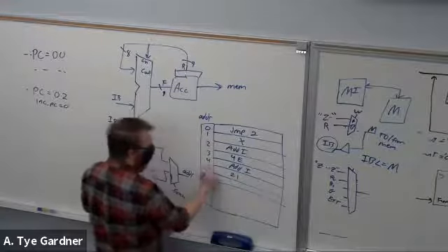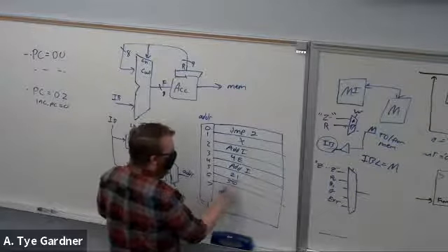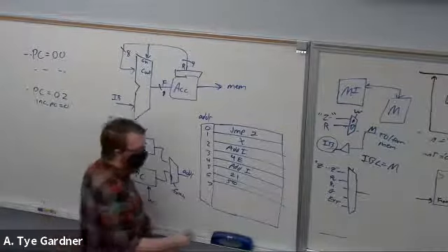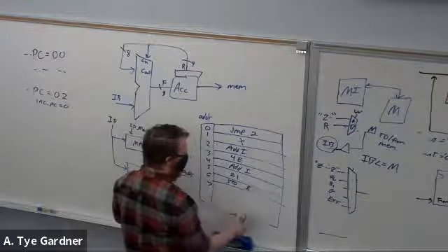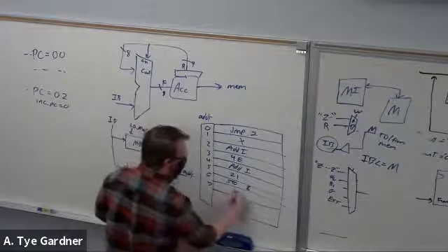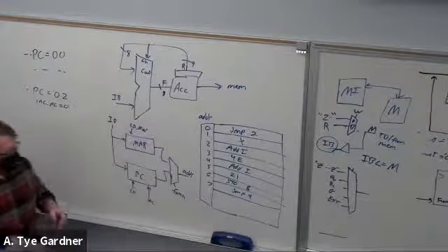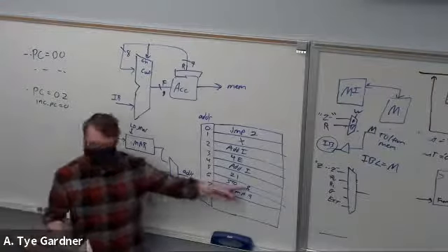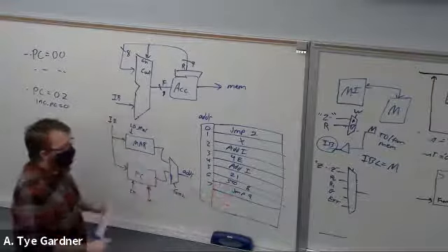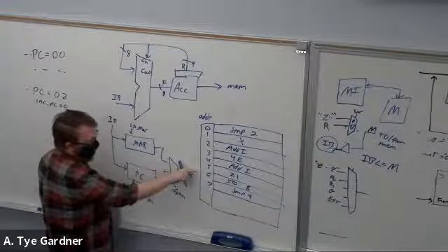21 or something, right? And then I want to store the result of that to memory. I need to remember that value, and I'm going to give it a location, say 8. But that means I'm storing a number in 8, and I have to do something with it, and that may be jump over it, or it may be, right? So what happens is we're stepping along in the process counter, add 21, store it to 8.